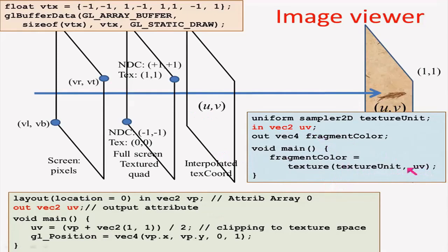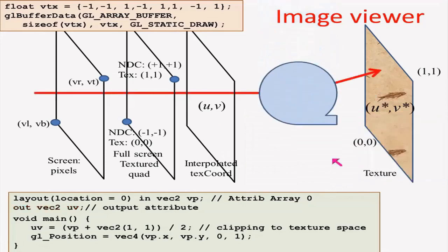Note that the sampler unit, called texture unit, will perform bilinear or mip-map filtering if it is configured accordingly. In the previous example, the texture was looked up at the location determined by simple interpolation. If we apply a distortion in address calculation, we can distort the image itself.